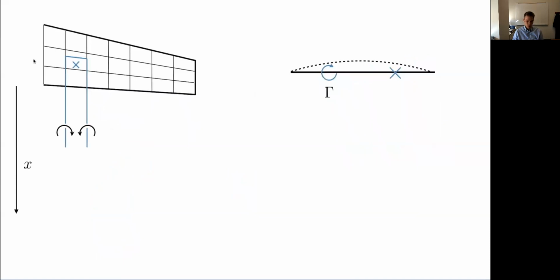Here's a picture of what that might look like for half a wing. It's going to be symmetric, so I'm just showing half the wing. We take a horseshoe vortex, but we can define multiple of them span-wise, as we've done normally. We can also vary them chord-wise. So here I've shown one at some chord-wise station, and I can have another one at this chord-wise station, another one down here, right? So I can discretize my wing both span-wise as well as chord-wise. This method is flexible. I can have sweep, just as we've shown here. I can have dihedral and so on, twist, all of those things.